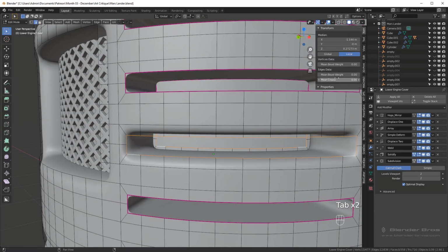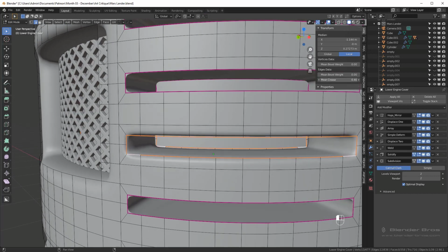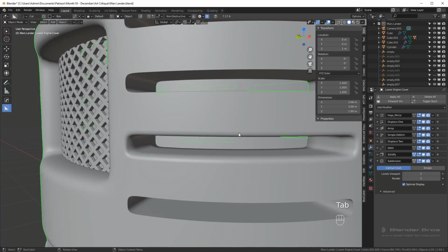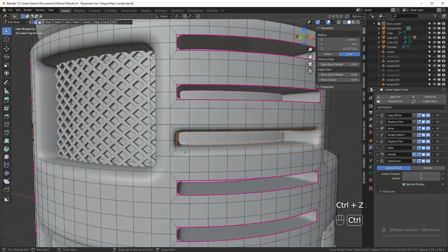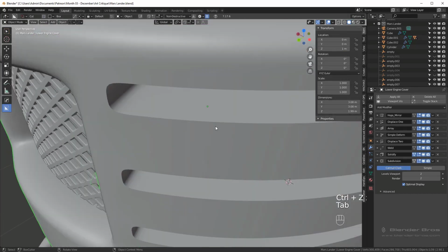And that's actually fine. This doesn't look awful really. I wasn't too sure why you ran a crease here. What you could have done is just tightened it up like this and made it more of a bevel than an actual subsurf. So I don't know if you're trying to add a bevel afterwards or what, but I wouldn't keep these fully creased because now we have a perfectly sharp edge which can exist in real life, and also you're not going to have those nice reflections around the corners like the bevels give you.